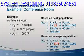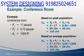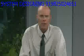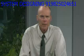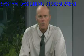So you can see, the more the population varies, the greater the impact of averaging. In addition, the taller the ceiling height, the longer the averaging time period, and the greater the impact. Of course, the hard part about this is estimating the occupancy profile. It's probably easier to do in some zones than others. For instance, profiles for classrooms or churches may be easier to estimate than for offices, theaters, or stores.